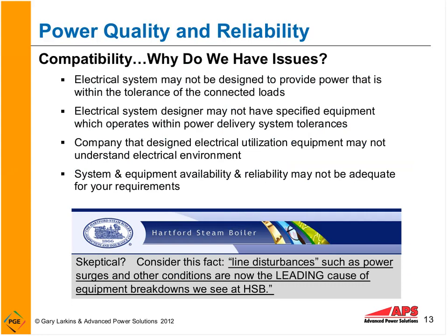Is the power system in our facility designed? In other words, have we designed it? Let's say we put a backup generator on this. Is the output of the backup generator going to provide the type of power that's necessary within the tolerances of that equipment? Or you may have an electrical system designer that may not have specified equipment that operates within the power delivery system tolerances.